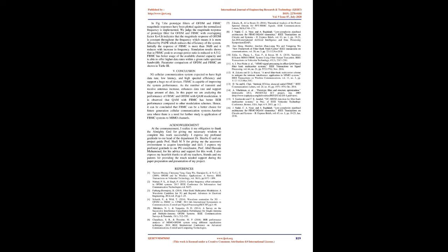Results and discussion. In the paper, the simulated bit error rate (BER), peak to average power ratio (PAPR), and power spectral density will be compared for OFDM and FBMC. This work uses QAM as the modulation method.